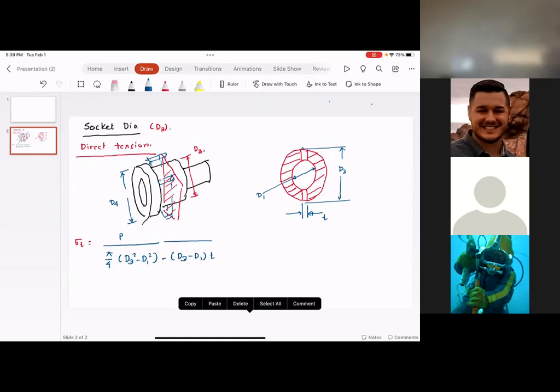In fact, what we want is, if the joint exceeds its rated capacity, we want the first element to fail to be the quarter because we can replace it. That's why even if you see that your quarter is failing in bending, that's okay. Just leave it as is.